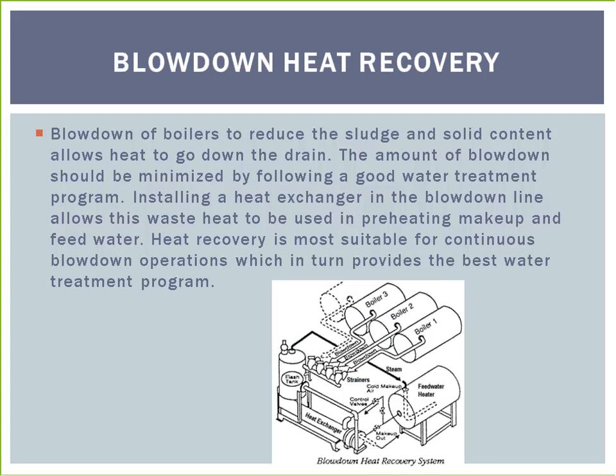Blowdown of boilers to reduce the sludge and solid content allows heat to go down the drain. The amount of blowdown should be minimized by following a good water treatment program. Installing a heat exchanger in the blowdown line allows this waste heat to be used in preheating makeup and feed water. Heat recovery is most suitable for continuous blowdown operations, which in turn provides the best water treatment program.